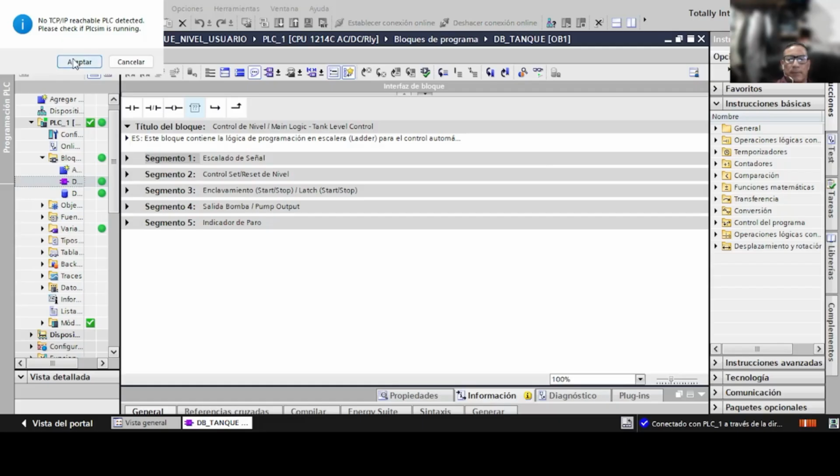Now, in this case, okay or accept. At this point, a network reachable PLC. The address of the PLC is this, and okay. And rack is 0, and slot is 1, and okay. Then start server. Here the status is running. It's okay.